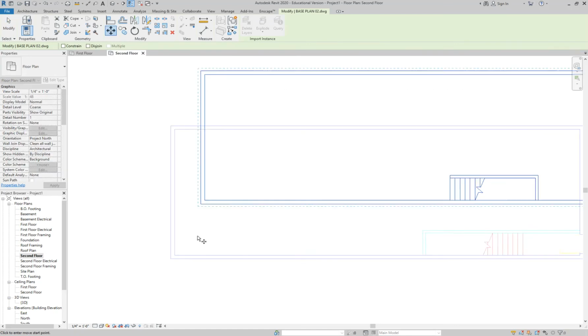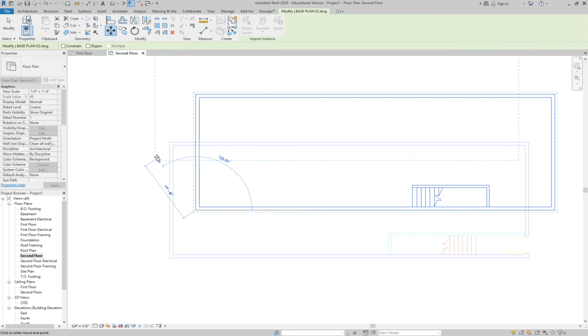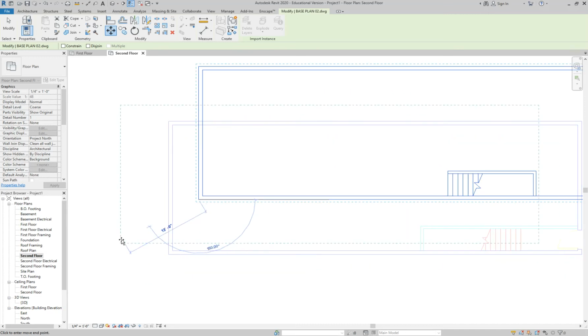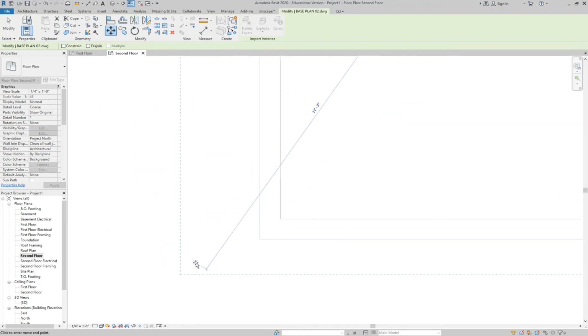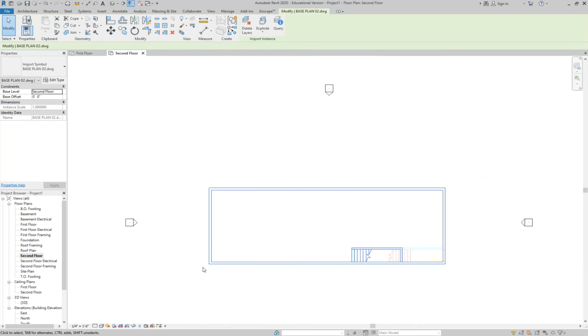So similar to AutoCAD, the first thing you need to do is the base point. Where are you picking it up from? So I want to pick it up from this corner, and now it's hard to see, but do you see those blue dashed lines? I wish they'd show me the whole first floor plan, but it's just giving me an idea of what I've picked up and where. So it still is that bottom left-hand corner, okay? And now I have to be confident that Revit knows what it's talking about. Find the other left-hand corner, and now they're stacked, okay?